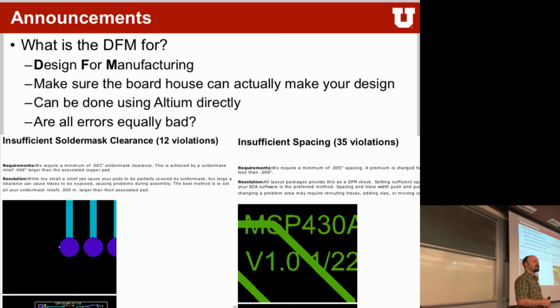Meaning that someone wrote in copper. Yes. In this particular case, somebody wrote text onto the copper plane, right? And ignored my comment, 3 comments in my class. I emphasized that several times. One of the big problems with this is if you have text on this copper plane, Altium lets you do that because sometimes you want to, like sometimes you want to put text on your copper plane because it can look nice, especially if it's gold plated. In this particular case, I don't think it was done intentionally, and what happens is that you now have traces that go over the trace, and sometimes they could short together.